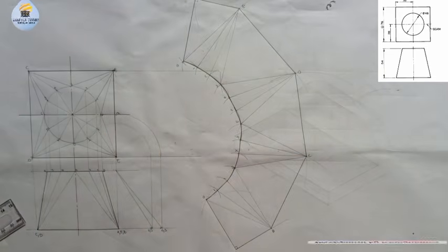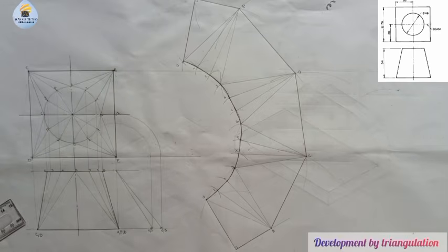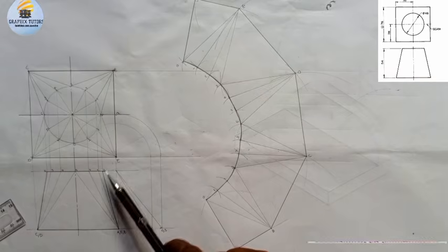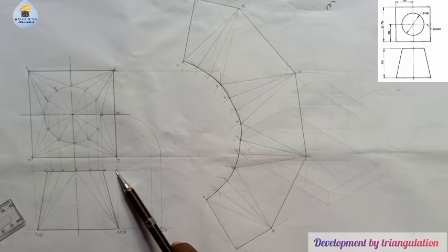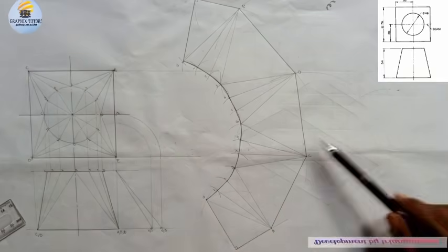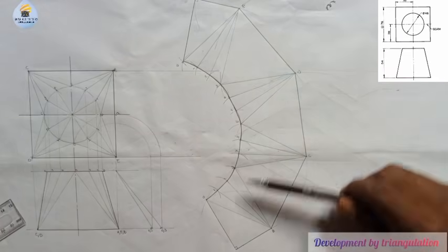So this is the development of this square here, right? We call it the triangulation method used to develop this. So just know one thing, that since it's symmetrical, this point you're seeing is for E, B, C, and D. That's what we use to get all what we have. So everything you see is taken aside from all these ones here.